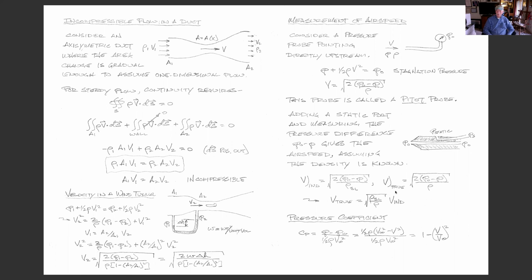And what you often do is you can dial in the atmospheric pressure and temperature of where you're flying to get rho. But the way an airplane flies, okay, if you're taking off out of Orange County on a standard day, here's all you need. Standard day, 59 degrees Fahrenheit.